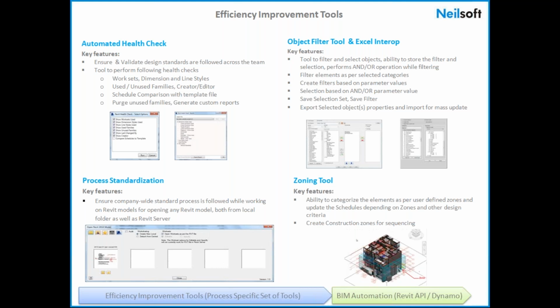So that is where we developed this tool, where a consistent workflow is maintained when users are interacting with Revit Server. So the way they are opening the files, or the way they are detaching the files from the local server, or the way they are synchronizing the files back to Revit Server, there is a consistent mechanism in which they are able to do that, so as to avoid any kind of confusion that may arise from not following a specific methodology while interacting with Revit Server.